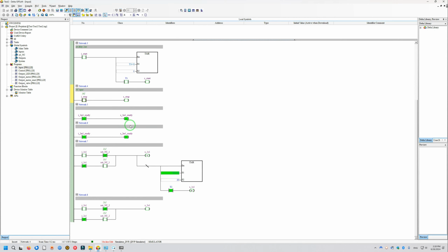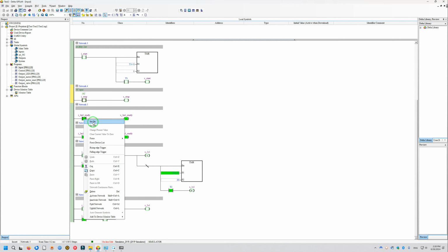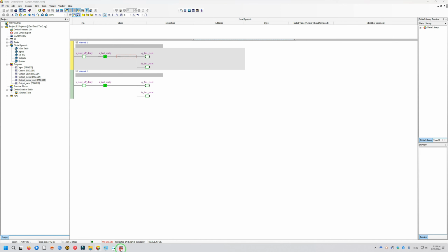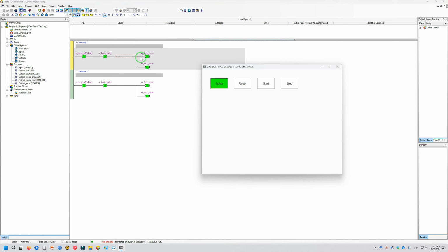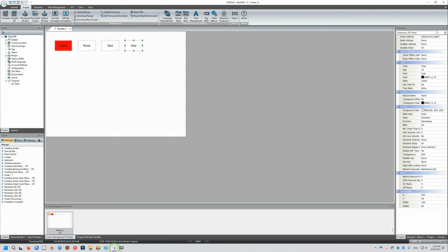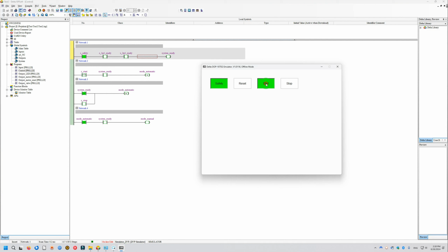the motor ready signal already exists, so I will switch it off. Let's go here and press reset. We are sending reset signal with off delay, as you can remember. We have 2 seconds of delay, although we have here, sorry, start button. System is not ready. This is why the motor doesn't go to automatic mode.